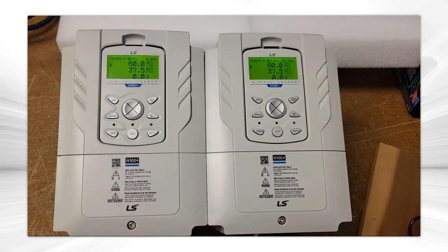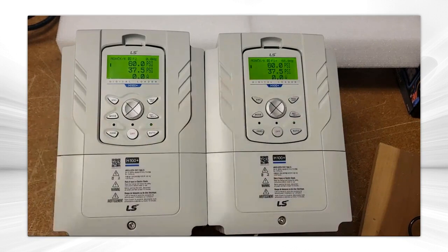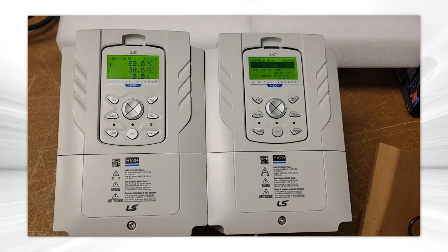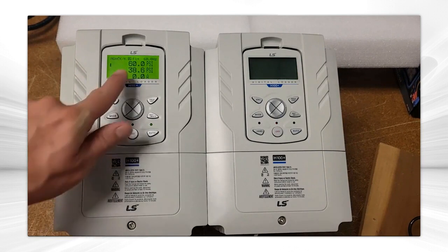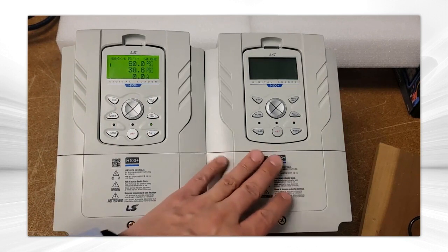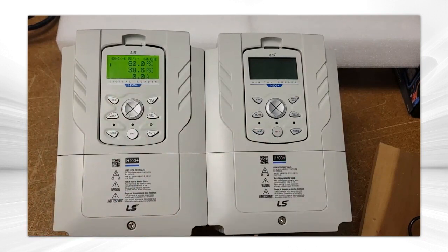All right, so the last thing I'm going to show you is, so this one is running 60 hertz. I'm going to shut off that drive. And you see that this one is running now, and it's ramping up to speed, and it's actually the master drive, and it's the lead drive now. So it's fully redundant. If this drive tripped out or there's any issue, and same thing for this one, you would see the other drive automatically take over for that.